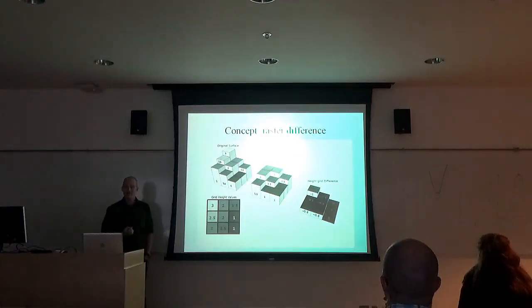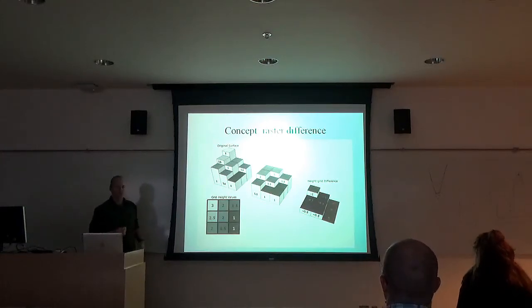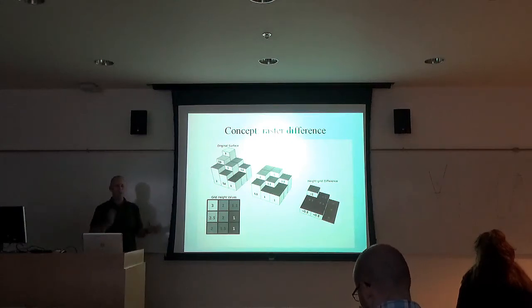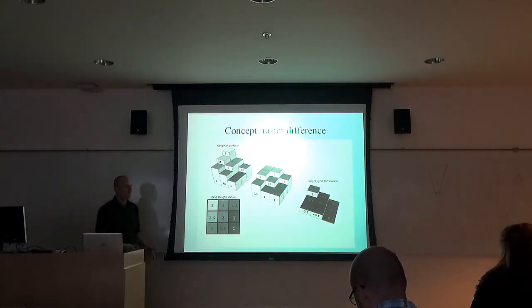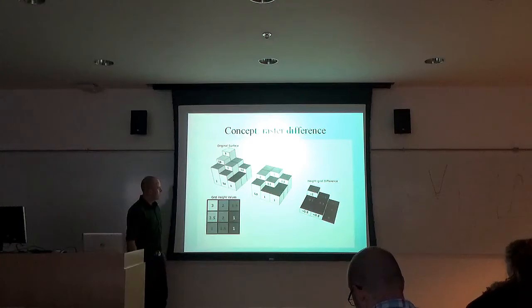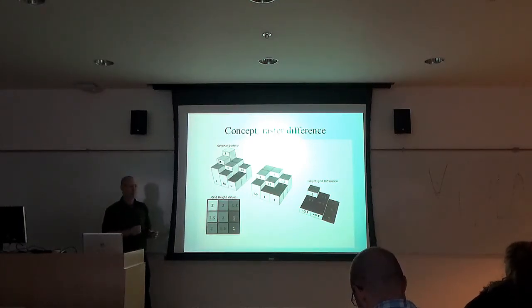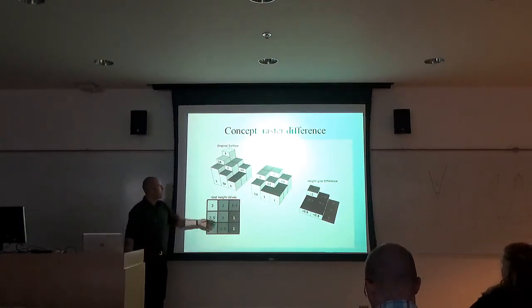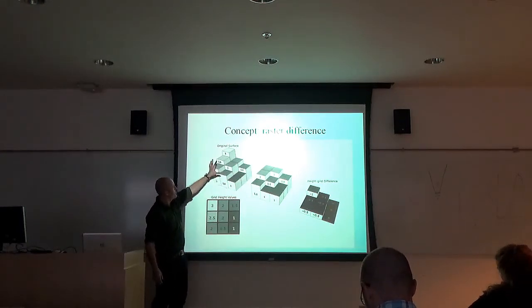And so I'm using a basic concept called raster difference. If you think of a raster map, every elevation, every DEM that you see in every GIS program, each pixel represents the elevation at that point, or it represents a data cell at that point. In this case, elevation. So here you can see how the pixels would more or less translate into 3D.